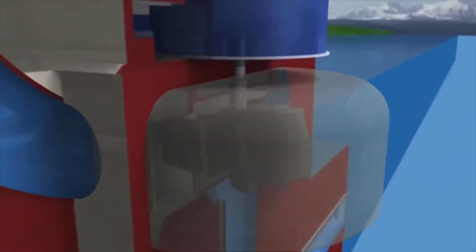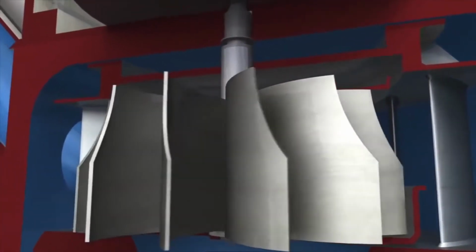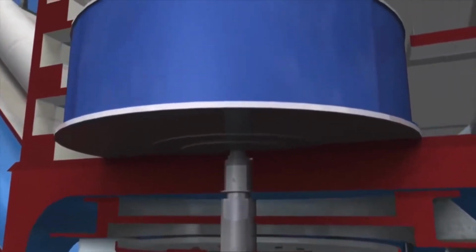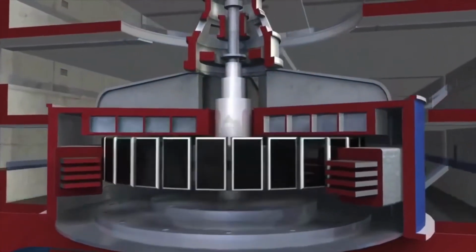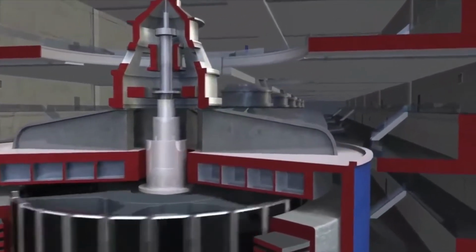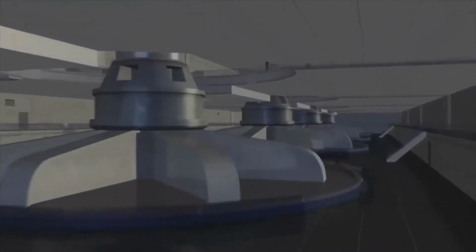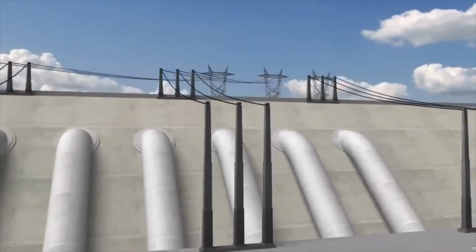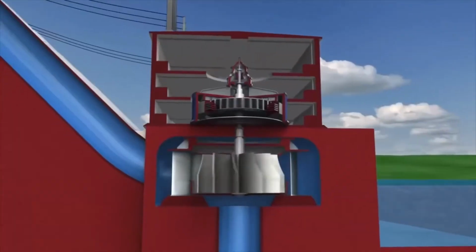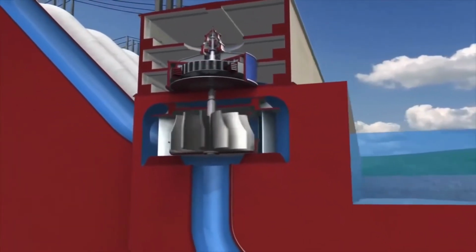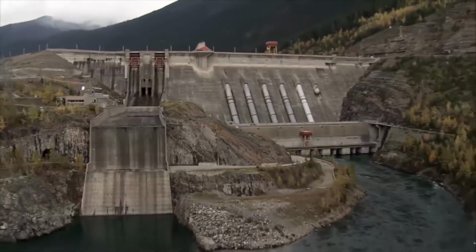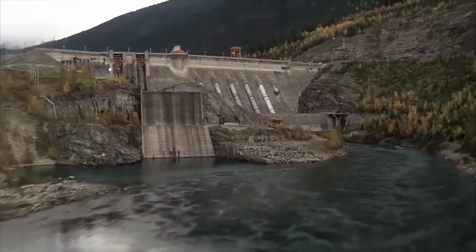Hydroelectric power plants are often built in dams that impound rivers, raising the water level behind the dam and creating as much head as possible. Because the potential power that may be derived from a volume of water is directly proportional to the working head, a high head installation requires a lesser volume of water to create the same amount of power as a low head installation. In a certain dam, the powerhouse is built on one side of the dam, with a portion of the dam serving as a spillway to dump excess water during floods. The powerhouse may be positioned within the dam itself, where the river flows through a tight, steep valley.